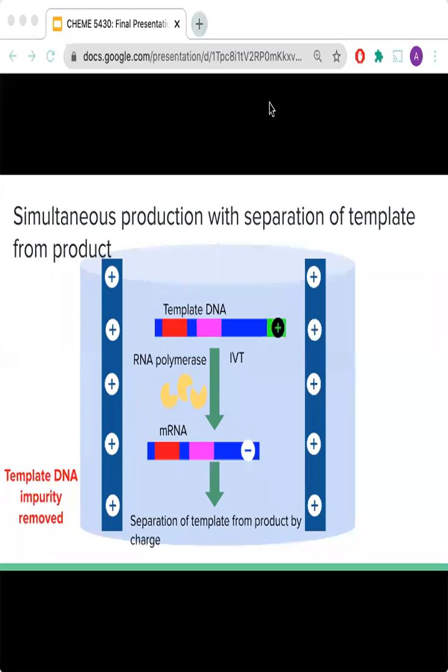We propose to have a continuous system where the production occurs in a temperature-stable bioreactor, placed above the purification columns, and have the production flow into the column after production occurs, thus removing the need to remove and transport product. This process would have to be tested and validated as there is limited information currently available on mRNA vaccine production. This could also potentially decrease points of contamination and reduce costs as well.